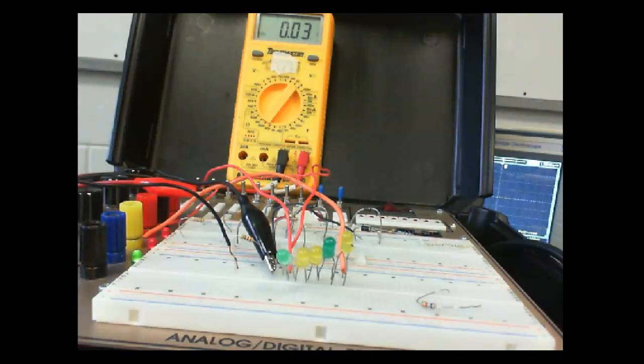So anything I need to have a constant current, I can do what? I can use a transistor. I set the current with a what? With an emitter resistor. So we call this emitter bias. And the transistor automatically compensates its resistance to try to keep that current flow.